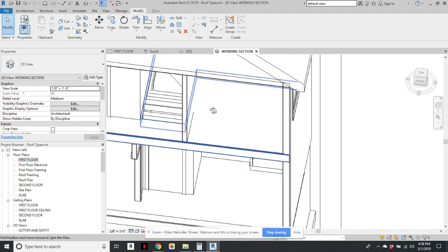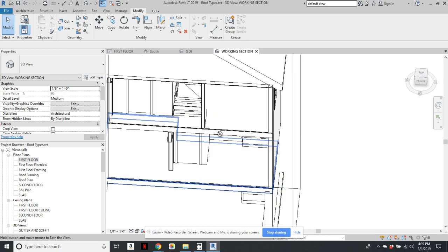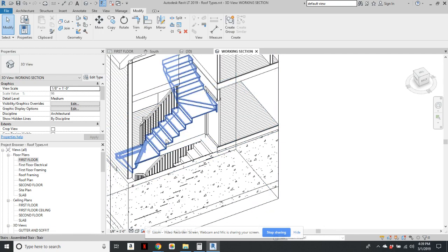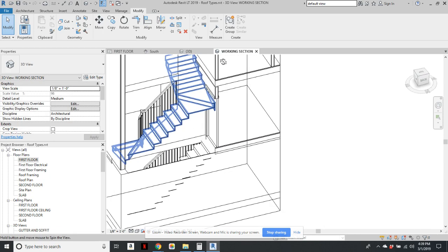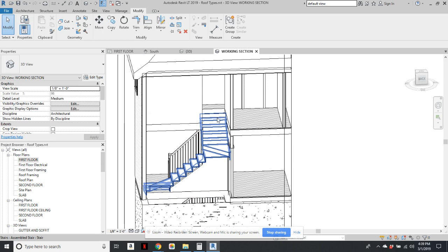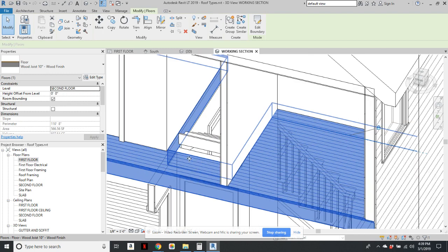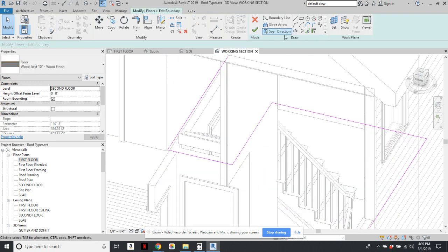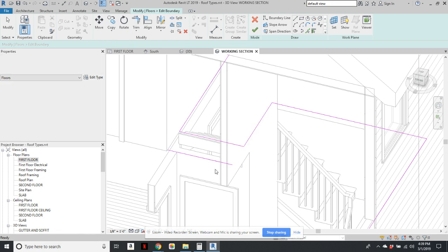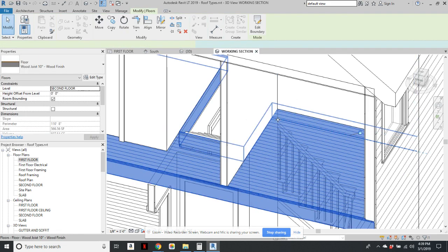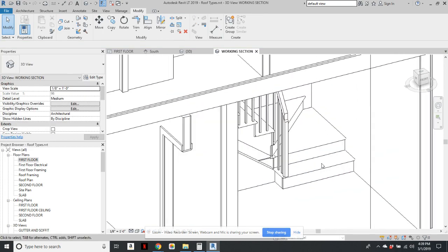You can do that easily once you know what the dimensions need to be for the new set of stairs. These stairs are a bit shorter because we were able to take up treads by putting them into the landing spots. Because we were able to put them into the landings, we don't need them to stick out as much into the hallway on the second floor. So the floor area obviously needs to be adjusted so it matches the new stair position. We would just edit the boundary and make sure that the new boundary for the floor hits the stairs. Whoops, I'm drawing way more lines than I should here. Let's trim that around the stairs, and that should correct the size of that opening. And we've now created a custom set of stairs that has the winders.